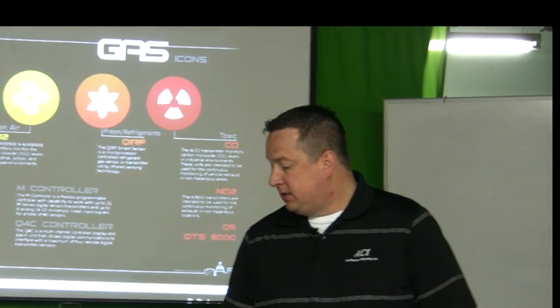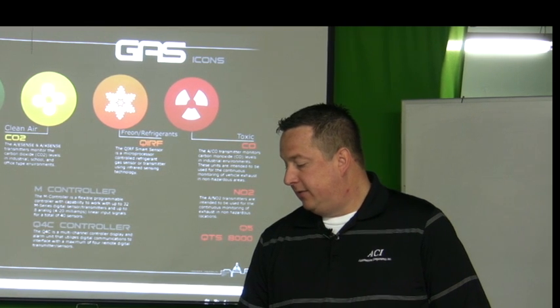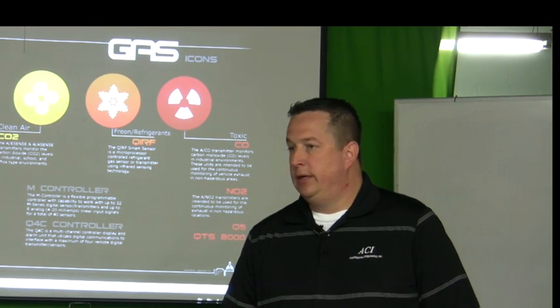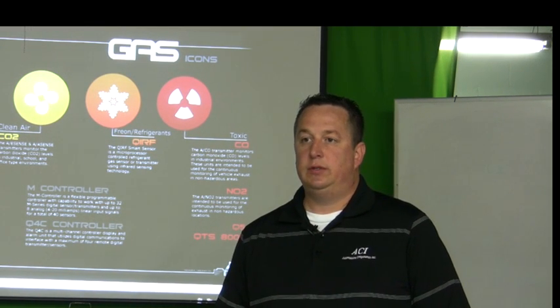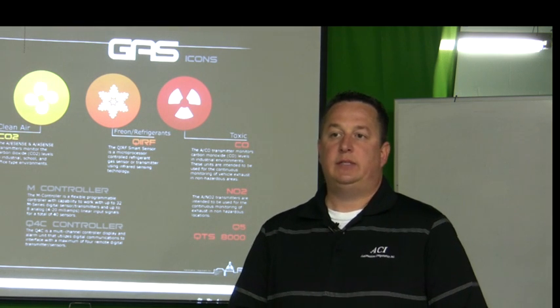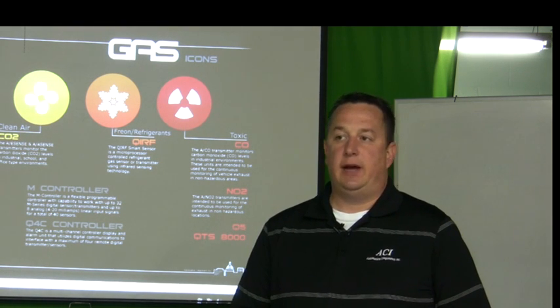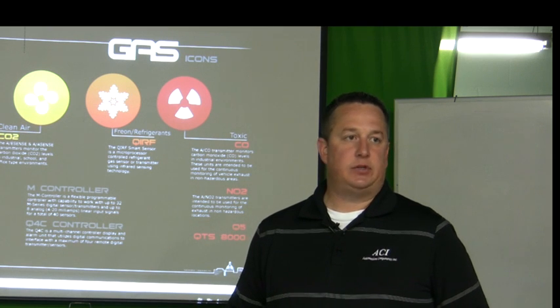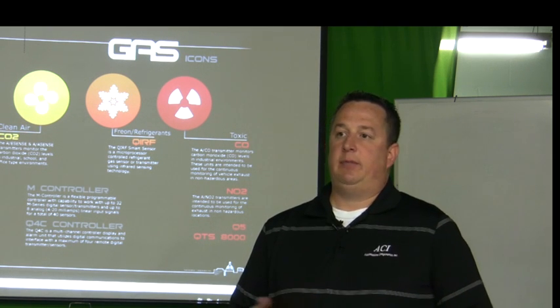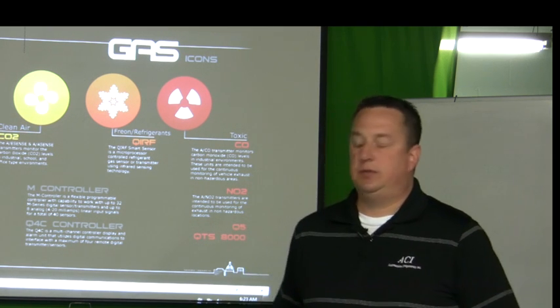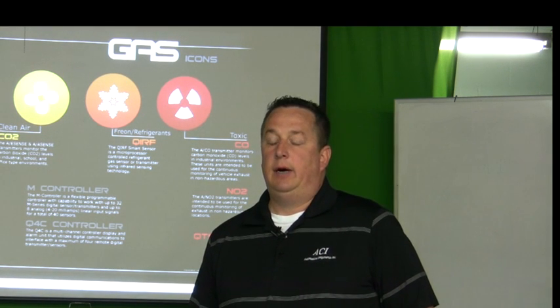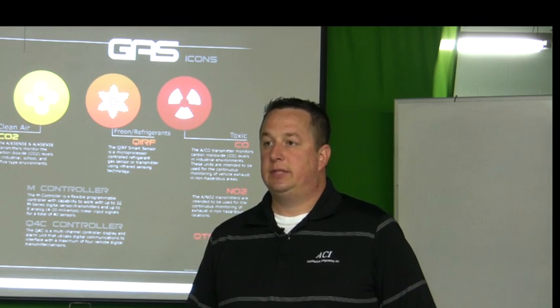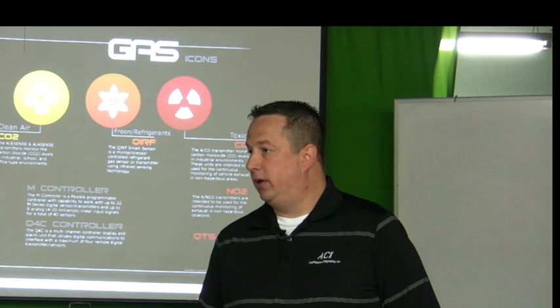Any type of combustible, like I said, freons, refrigerants, CO, NO2, and CO2 are probably our three biggest sellers. I would say freon after that. So any type of demand control ventilation within classrooms or any type of commercial space, CO2 seems to be the number one gas detection sensor market that we are getting involved with.